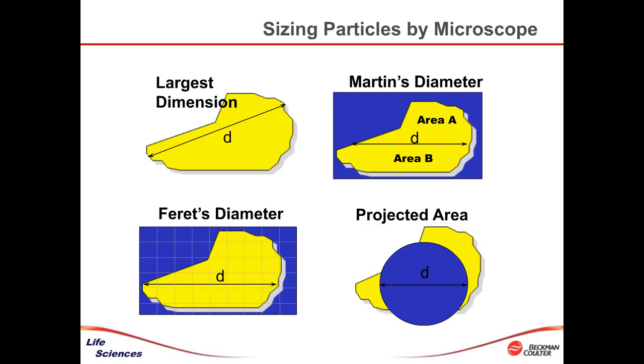But also, it would take a lot more time, especially if you have a good number of objects, to try to quantify a large number of objects in three dimensions. So this is a form of shorthand that gives us a pretty good picture of what's in the particular fluid, and if there's too many according to a standard. So in this case, we're looking at injectable pharmaceuticals. We want to know that it's below a certain limit. Ideally, you'd say, gee, if it's injectable, I'd like it to be 0. And that's certainly a good target, but it's also usually a very expensive one to achieve. So it has been found over years that the limits that have been used here, 6,000 per container at 10 micron and 600 per container at 25 micron, are effective enough controls. The human body can deal with that in a reasonable way.